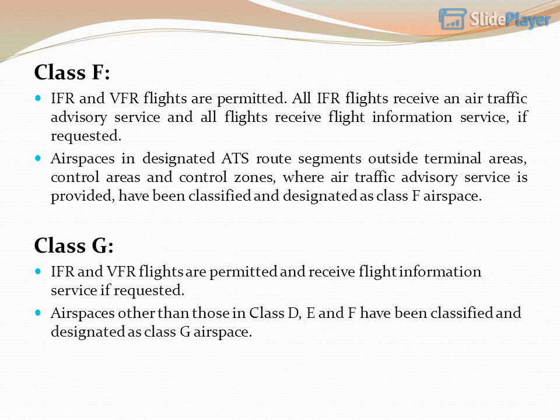Class F. IFR and VFR flights are permitted. All IFR flights receive an air traffic advisory service and all flights receive flight information service, if requested. Airspaces in designated ATS route segments outside terminal areas and control zones, where air traffic advisory service is provided, have been classified and designated as Class F airspace.